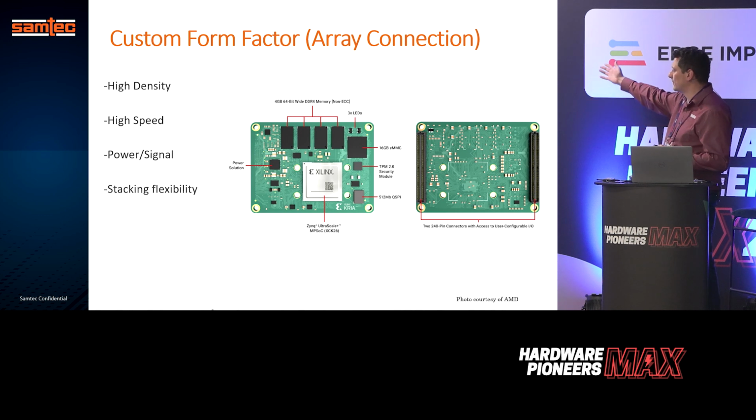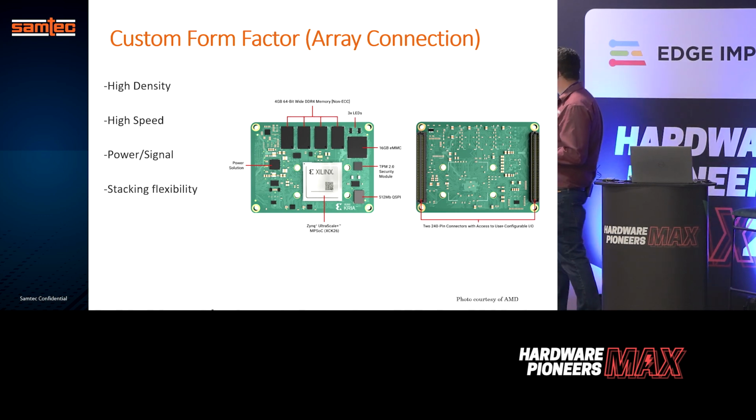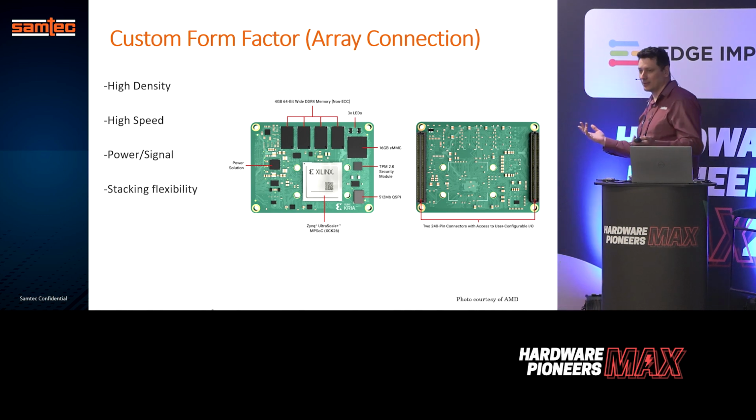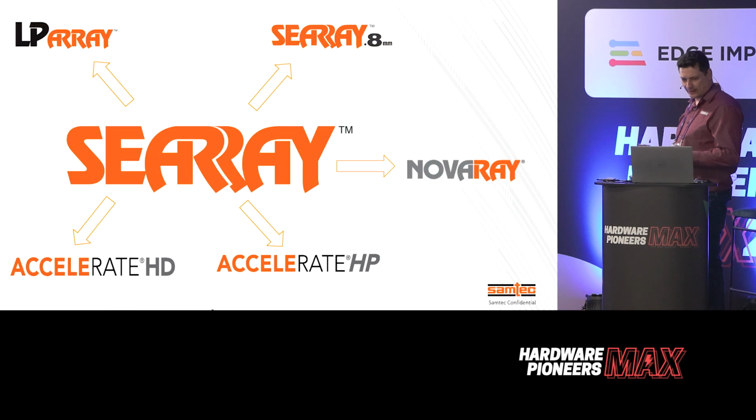So you can go up to 400 pins, or you can go down to 40 pins. The 40 pins is basically the size of probably a 20 pin or a 10 pin 2.54 pin header. So if you want to miniaturize your devices, you will need to start to move into smaller pitches. So this is a little bit about the evolution of the array products.